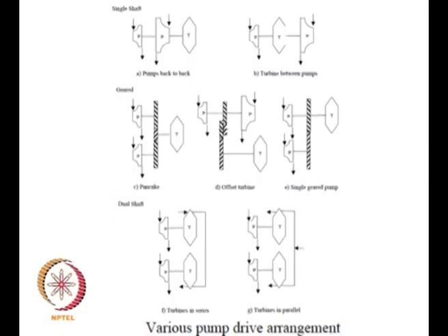There are other arrangements that are used, this is known as some pancake arrangement. Now in this arrangement there is a turbine between the pumps. The turbine and the pumps are run at different RPM and they are connected through a gear train. Okay. In the first one there is no gear train connecting the pumps and the turbines. So whatever RPM the turbine is running at, the pumps are run at the same RPM. Here you have an extra control on the RPM of the pumps. Okay.